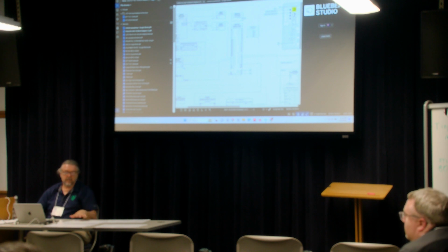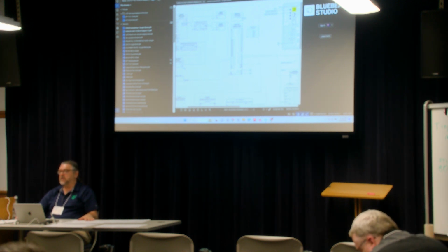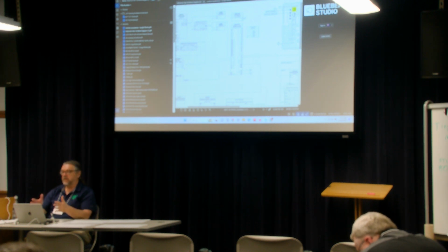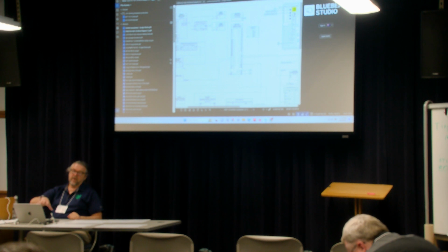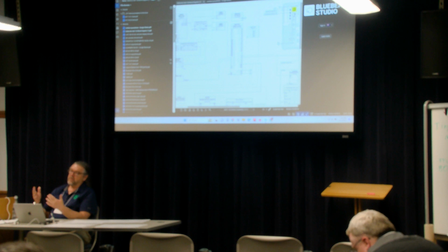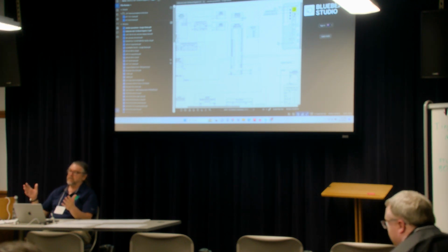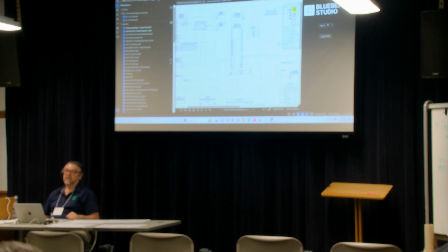Yeah. And one of the things I said I would cover is how to take a cheap tablet to the field and have your electronic drawings with you. Have the paid version of Bluebeam, and create a studio session with the drawings that you want in the field. On your cheap tablet, you install a demo copy of Bluebeam, which will forever be read-only, but you can read studio sessions and mark them up. Then that's what you take to the field.